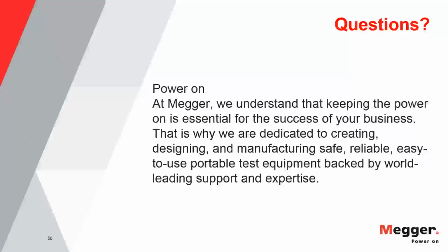But again, the apparatus is different, the principles are different, and for the cable testing specifically for the cable assets, you want to do offline testing because that's the only really suitable way of doing that. For instance, one major shortcoming of online monitoring in terms of cables is that online PD is pretty much absolutely not suitable for longer cables, and most of the cables are also not accessible.